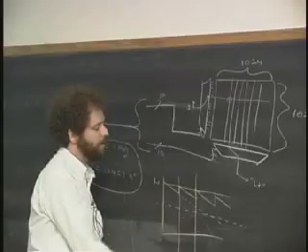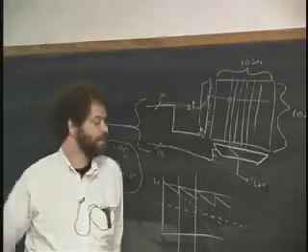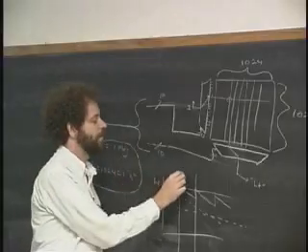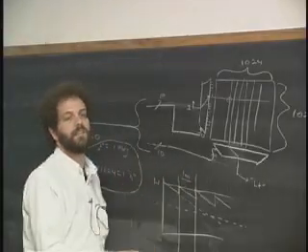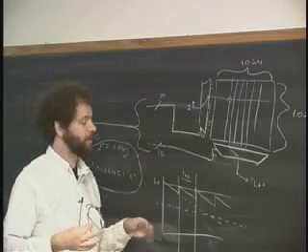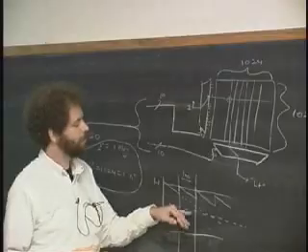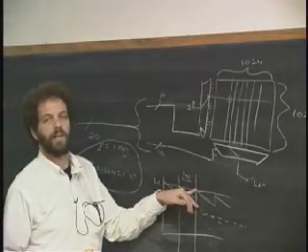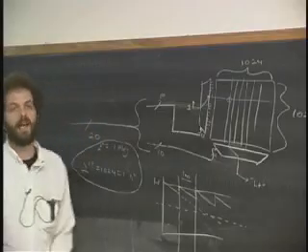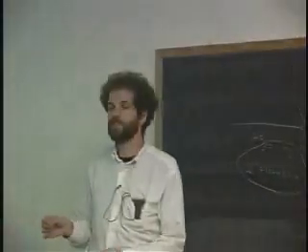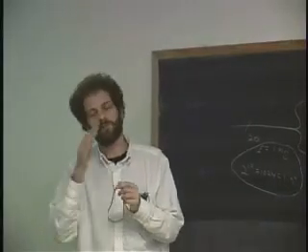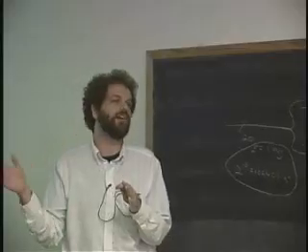And it turns out that every computer, including this laptop here, checks every bit in the entire system every millisecond, every thousandth of a second. Every bit in the system is being read, restored, in other words, checked whether it's high or low, and being restored back, written back at a higher value. Okay? So that's a pretty cool thing. And it turns out that there are special mechanisms inside of the circuits themselves, so the microprocessor doesn't have to go through and read all the millions of bits that there are out there.